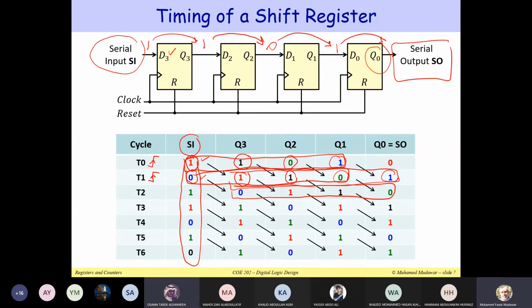So if you asked us in the exam or in the quiz, if we reset, we start at 0, 0, 0, 0. And then every cycle, you can provide one serial input and you start shifting it. In some cycles it will be 1, sometimes it is 0. So eventually, you can have any pattern. You can store 1s and 0s inside these flip-flops and start shifting. Like it's given already. Yes, so the input must be given to us. So the serial input is given to us, and we are keeping track of the bits which are shifted inside these flip-flops, inside the shift register.